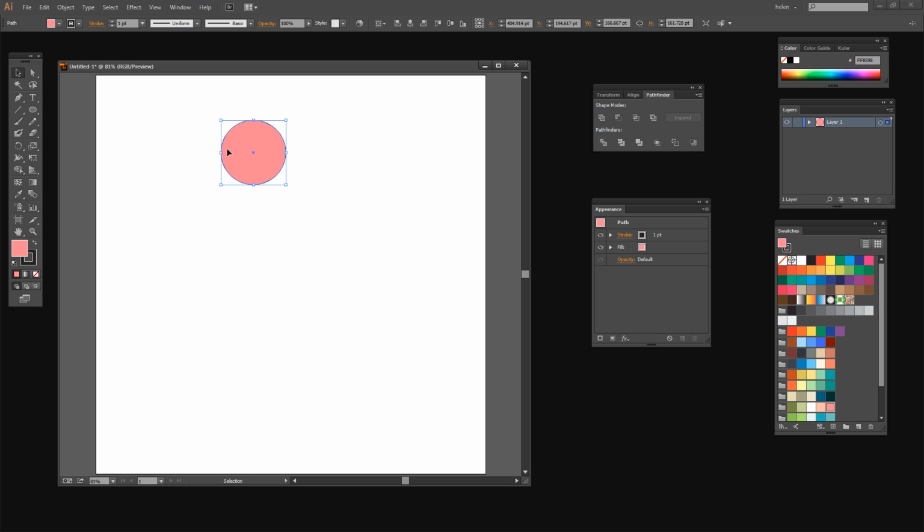And then I'm going to add 4 other circles around the bottom of it. So I'm going to click again on the ellipse tool, and I'm going to hold Shift this time as I drag out 4 circles. Now if you want these to be exactly the same, you could just create one and copy and paste the others. But I'm not really that fussed here. Now I'm going to line them up, and I want them to be slightly overlapping. I don't want to see any of the underlying ice cream through here. So I'm going to move these all into position, and this is going to be my basic shapes.